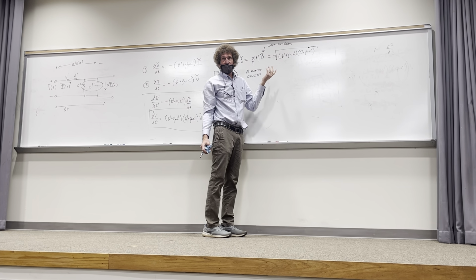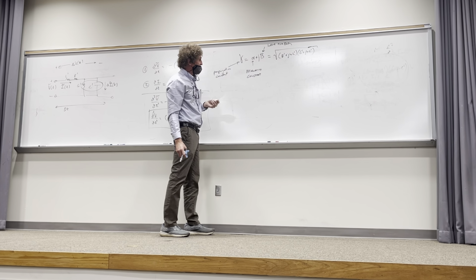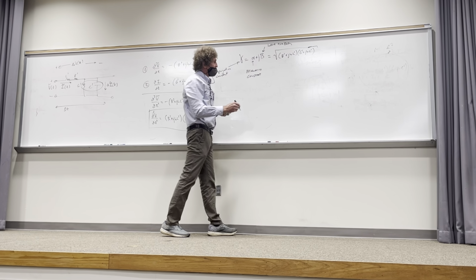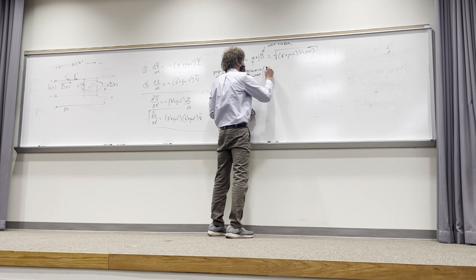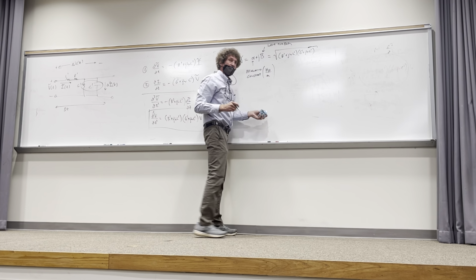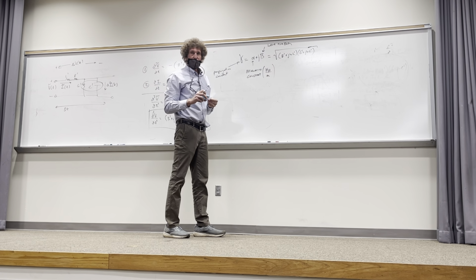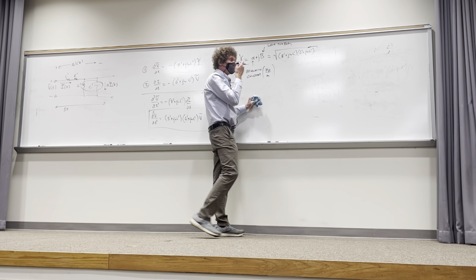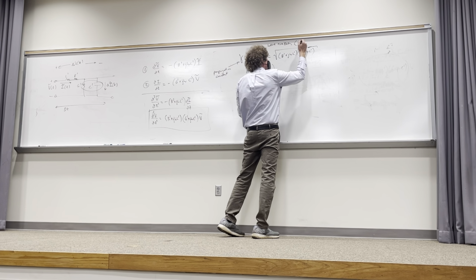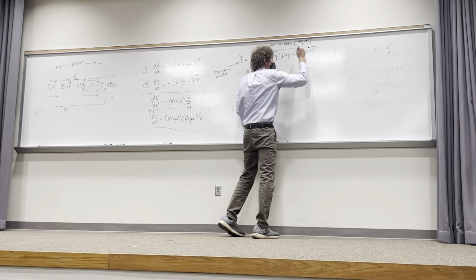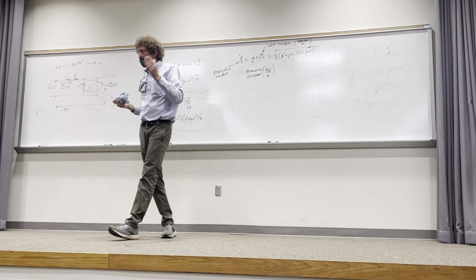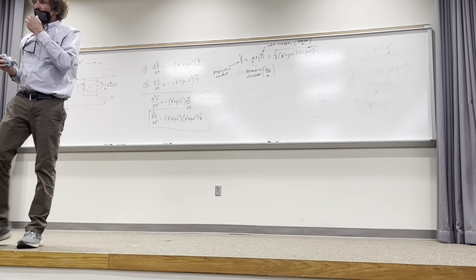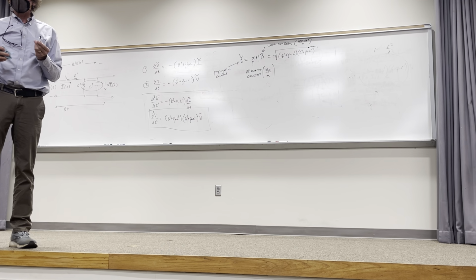So that makes sense. What we do is take the real part and define it as an attenuation constant. The units of the attenuation constant are Napiers per meter. That's not that important yet. And plus j beta. J beta is a wave number, and wave numbers have units of radians per meter. Now a radian is a measure of angle, so that should clue you in that we're talking about a phase relationship, as soon as you hear radians per meter.